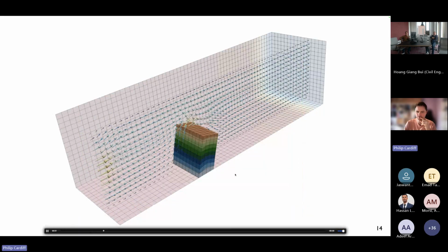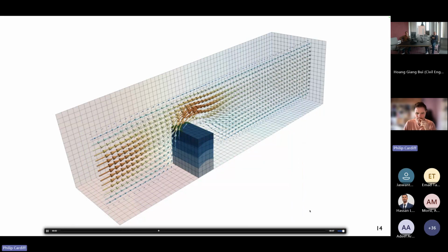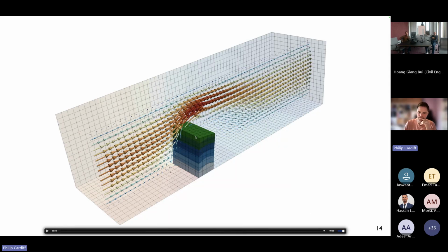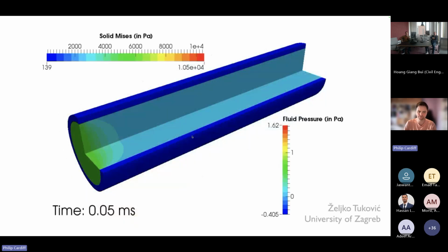And here's another tutorial from solids4foam of a kind of standard simple benchmark of flow over an elastic beam, and this was transient, but there's various different formulations of this benchmark to check your method works. They're solving finite volume solid mechanics in the solid and finite volume fluid mechanics in the fluid, and then it's all coupled all within the same platform.